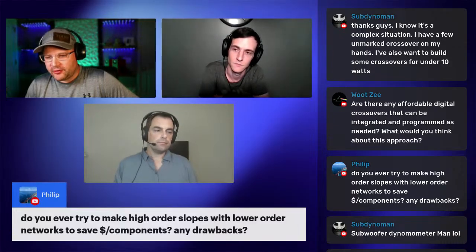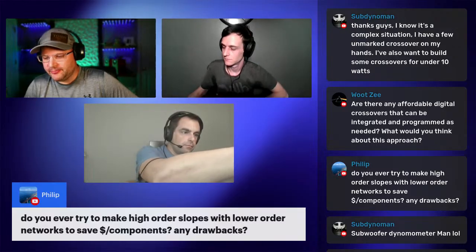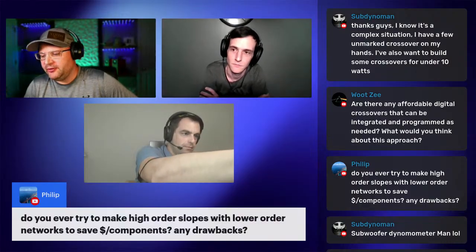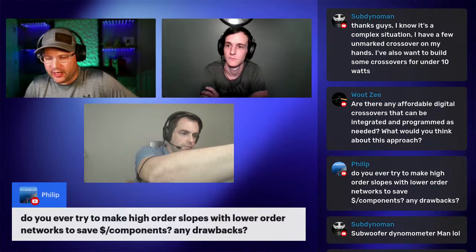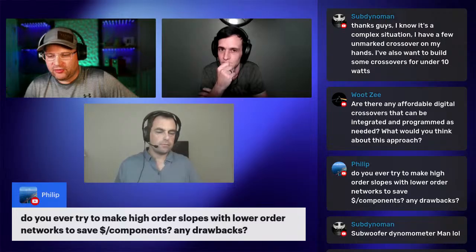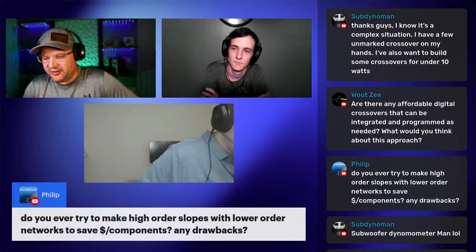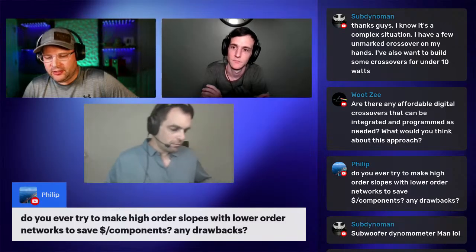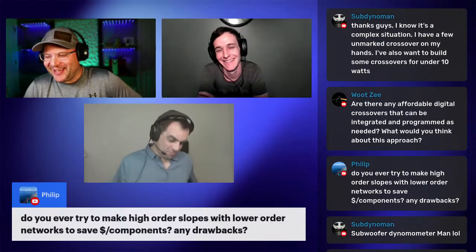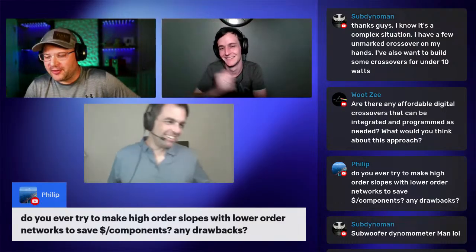I will tell you this. My favorite order on a tweeter, I almost always use a third order on a tweeter. Really? Oh, yeah, I do. For a lot of reasons. One, to keep the tweeter out of the woofer range, although I like to try to run my tweeters lower if I can, especially if I'm doing a two-way with like a bigger woofer, right? But the other reason is to keep distortion out of it. I know you don't care about distortion, but I do. And so, out of the crossover region as well.